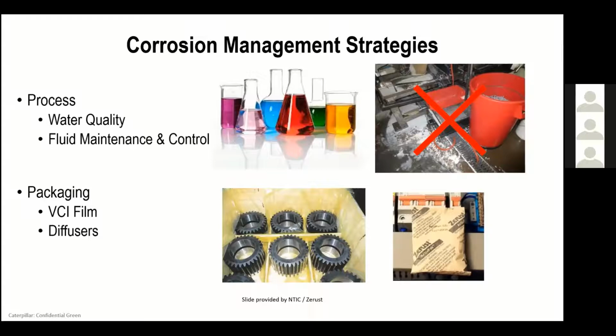So if you have any condensation that builds up there, you can handle some of that condensation, not a whole lot, but that's what it's used for. If you see any type of colored film, you can bet that it's more than likely going to have some impregnated amines in there to provide corrosion protection. And then over on the right, Northern Technologies is showing here, in this case, probably an emitter. It could be a desiccant, but it's providing additional VCI, volatile corrosion inhibitors, to that packaging.